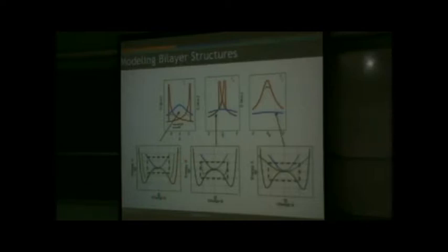What I'm plotting here is C versus V, capacitance versus voltage. The red curve shows ferroelectric plus dielectric. That PE here means paraelectric, but it's basically a dielectric. So it compares the heterostructure capacitance with the paraelectric capacitance.